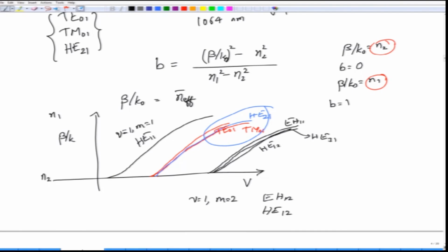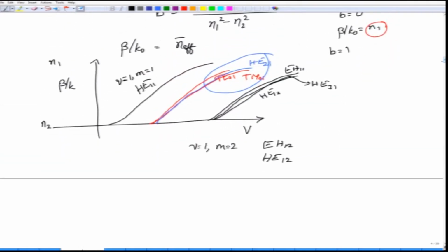So, you will see that for a corresponding value of nu equal to 1, you will get additional terms, but these terms do not always come in one sequence that you might imagine, because these sequences are heavily dependent on the solution of that equation. But what you have to note here is that until this 2.405 normalized value of V, you only get single moded propagation, and this would actually be the maximum value of the single mode propagation constant that you can get, because beyond this, if you increase V, you want to reach for this propagation constant, but unfortunately you are also going to induce other higher order modes. So, this is what happens.